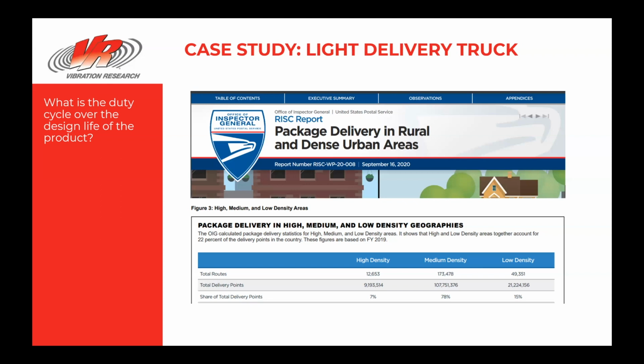The main idea, as Mark presented in last month's webinar, is to establish a field damage level to characterize the overall life exposure of the product. This, in turn, is used with weighted fatigue damage spectrum of the road load data acquisition, or the surrogate data, to generate the accelerated vibration test. The test is accelerated to stay within the bounds of the shock response spectrum of the field environment.